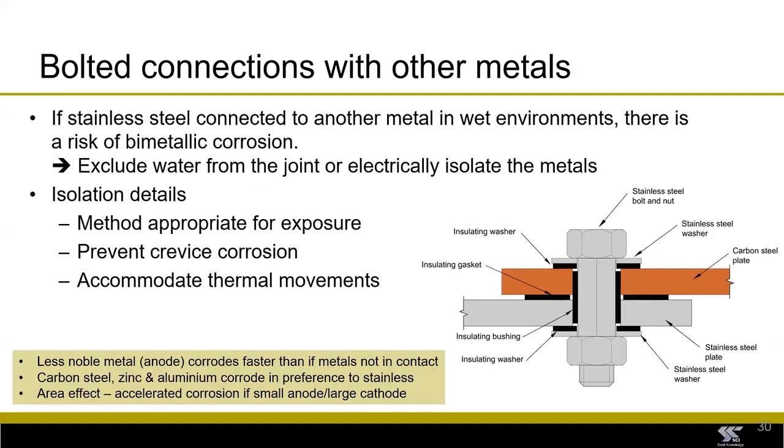Finally, on bolted connections, what to do if you're connecting with a carbon steel member. Again, there is guidance in all the design guides and specifications about this. It's not a problem if there's no water. But if there is water, and particularly if it's salt water, then consideration needs to be given to either exclude water from the joint or to isolate the metals.